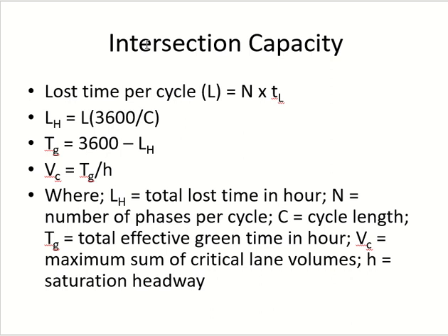Now, I have the loss time for the entire hour. Then this is the effective green time of the entire hour. Effective green time means what? The time during which vehicles are moving at saturation headway.